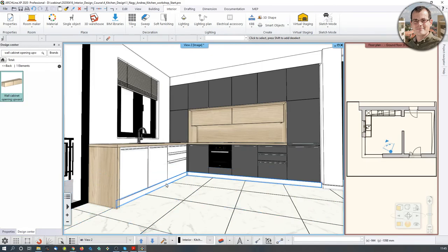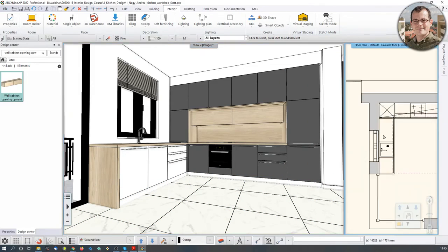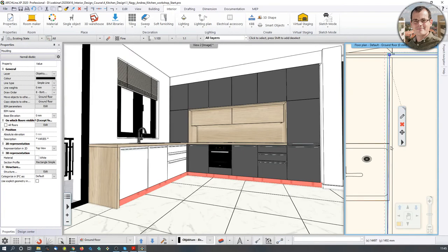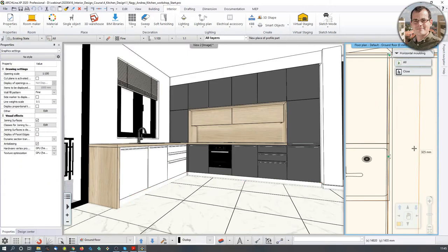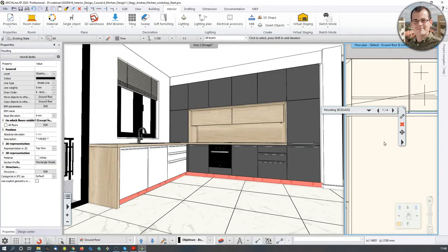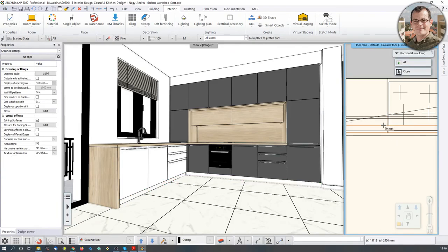One thing you could be customizing if you need it is where this plinth actually is. If you highlight the plinth, which is over here, you can click on the nodes and the sides, and you can offset things back and forth. So if I want to offset it a bit backwards, maybe 50 millimeters, you can do that like that. You just hit offset and move it backwards.